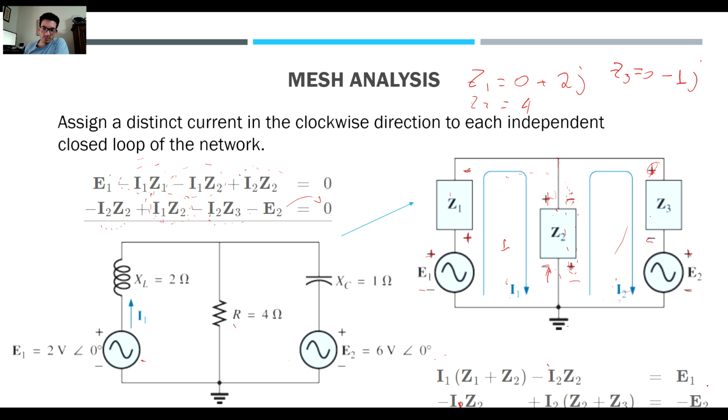So if you remember, last time for DC circuits, we decided to do a system of equations where if you organize them like this, with columns being I1, I2, and the independent source, then you can solve this using a system of equations. You can solve this however you want. Go ahead and try to solve using Python or MATLAB, or see if Excel can solve it. See if you can do it by hand. But the point is that Z, the impedance, has an imaginary term, so be careful when you do the math. That's why I think you should practice using a calculator.